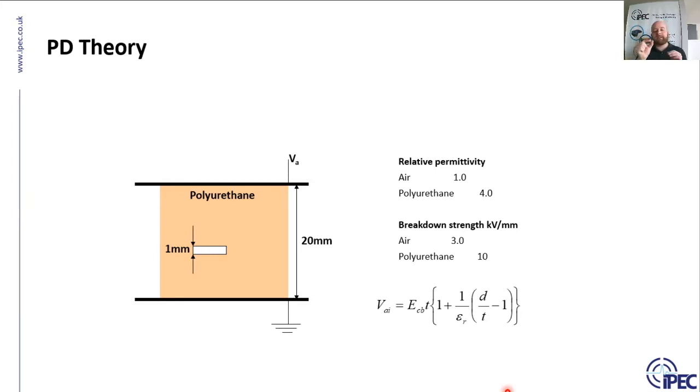What that means is, instead of a uniform dissipation of the energy from the conductor, you get a localized area of capacitance, a localized area of stress. So as the energy in the power cycle increases, the stress very specifically at that defect point increases also. And as that stress increases within normal working voltages, you will get a very small, low energy breakdown across that defect. So it must be noted that breakdown is at the defect.